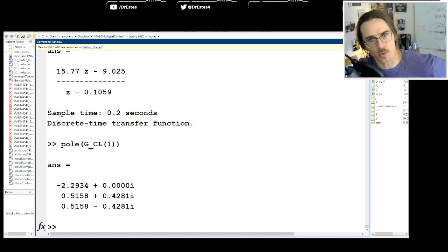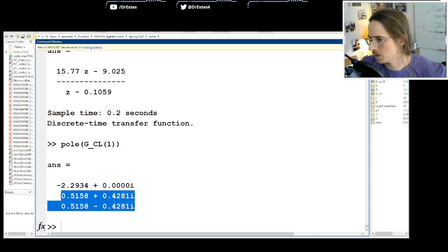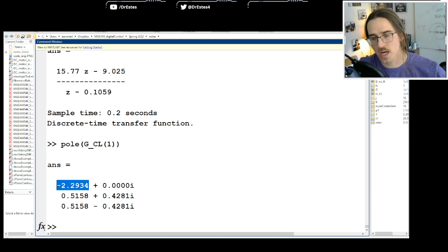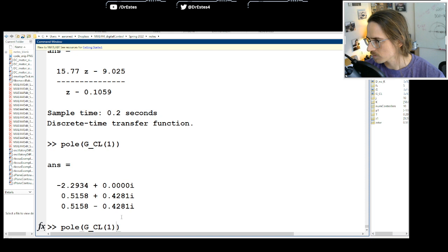This is unstable. Look at this. Two of these roots are located at Z star. That's great. But our third closed loop pole is on the negative real axis, and it's outside of the unit circle. You get a different answer? Do other people get the same answer? If people are getting the same answer, then that's good. If nobody's getting the same, but I think this is right.